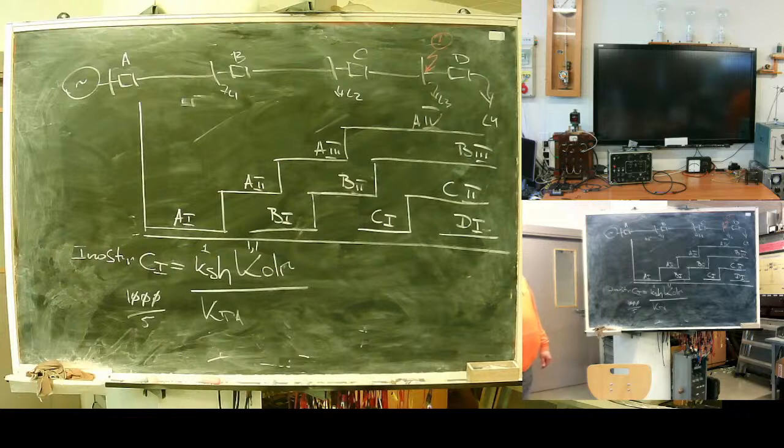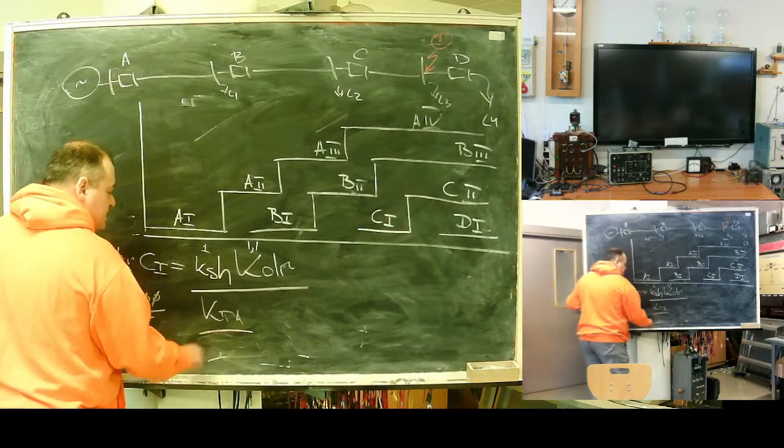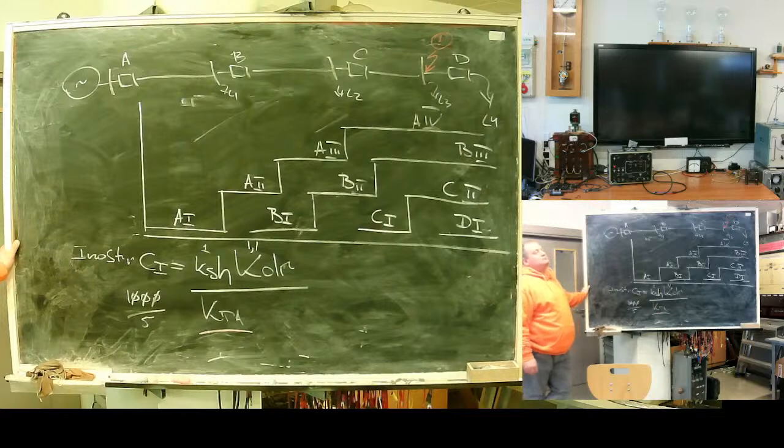Anyway, there will be a secondary current. But one more thing: there are relays where you program secondary amps. That means you account for your current transformer ratio when you calculate settings. Or relays where you program primary amps.